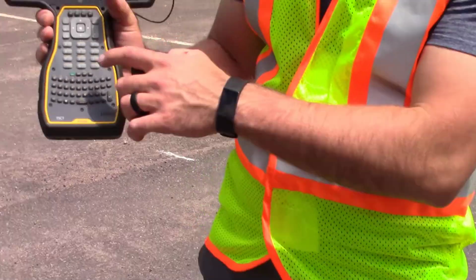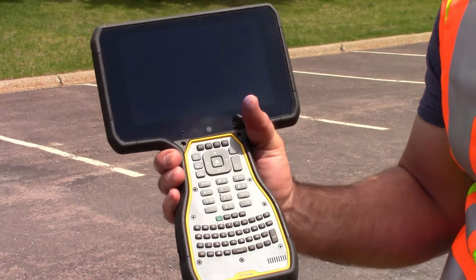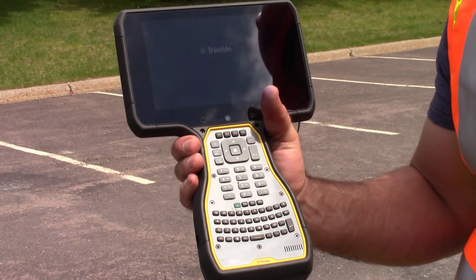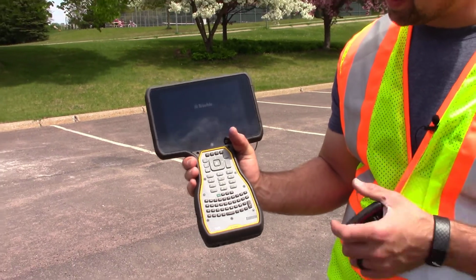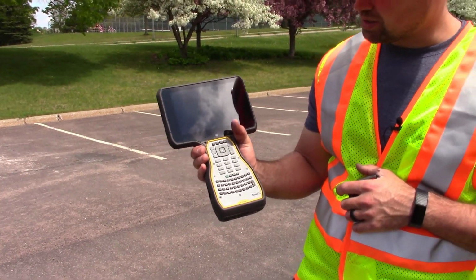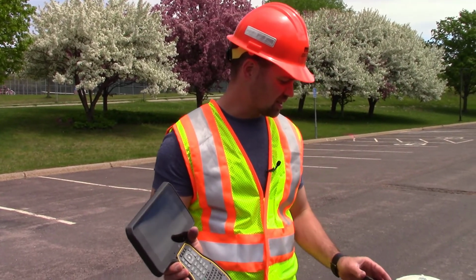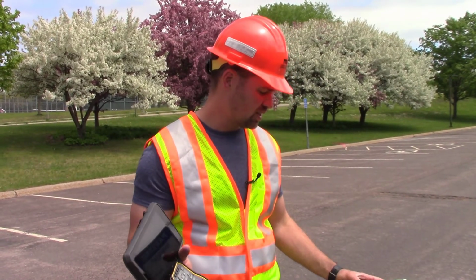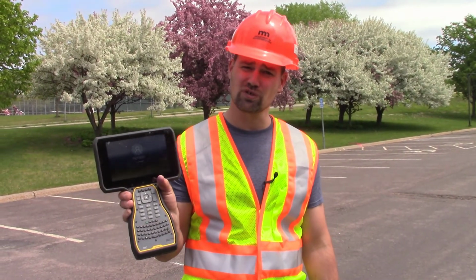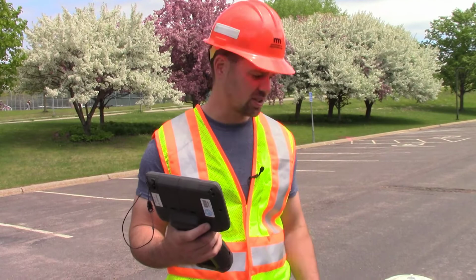And then the last thing we'll do is turn on our Trimble TSC 7. And you see the Trimble logo coming on. That means that we have all 3 of our components now powered up, and we'll take you through the process. You're actually done with your MiFi and your R8 at this point, and now everything is controlled here from your controller, and we'll make sure that these 2 components are working properly to get our corrected GPS string coming out of the R8.